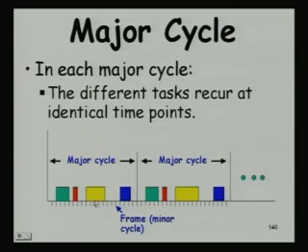So, it is not necessary that a task has to run for the entire duration, and that time will be idle basically. If a task completes early, it can't use a full frame, and that much time is idle. But we will see later, when we look into more details of this, that if it completes early, then we can schedule some of the tasks for which a static schedule was not developed.